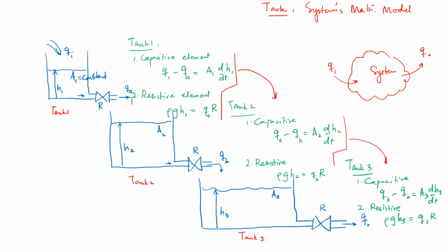So for that particular arrangement, what you need to do is to go through kind of a laborious arrangement where you can use the equations for tank number 1 into tank number 2, and from there into tank number 3 to construct the nth order differential equation.